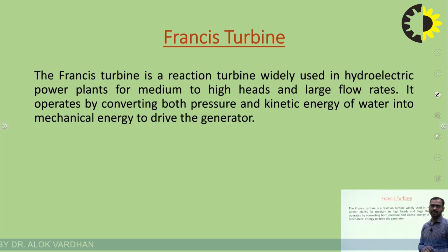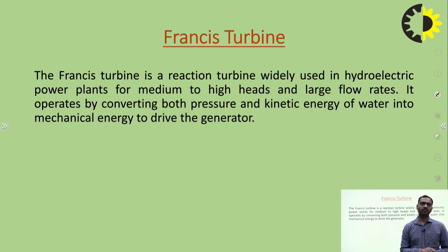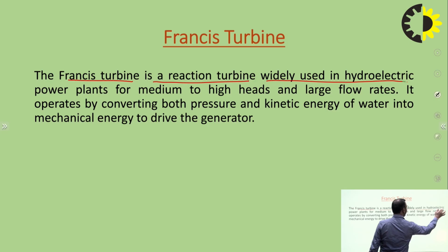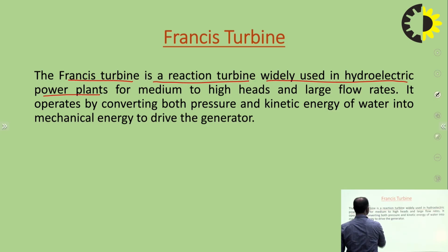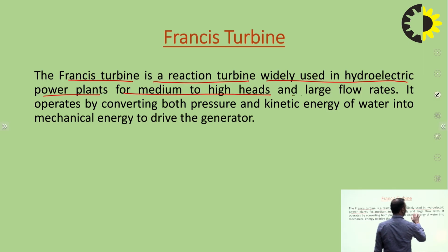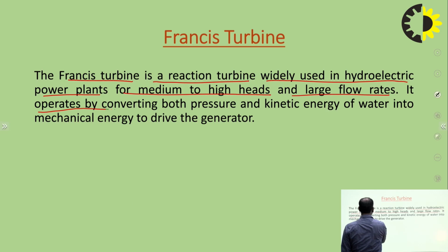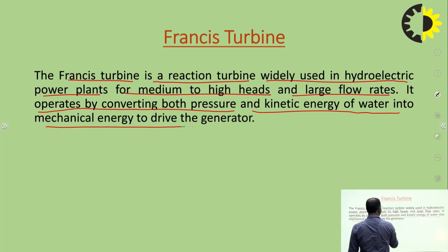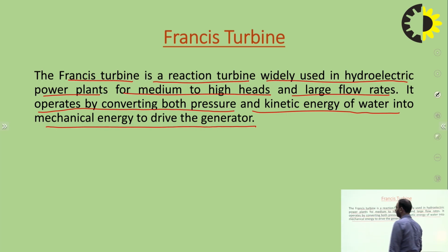Now I will discuss construction and working of Francis turbine. So basically, Francis turbine is a reaction turbine widely used in hydroelectric power plants for medium to high heads and large flow rates. It operates by converting both pressure and kinetic energy of water into mechanical energy to drive the generator.